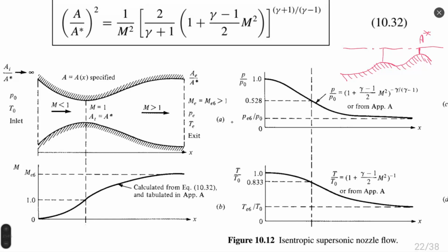And in the previous extreme minimal, this part where we had the minimal area of flow is not a throat anymore. Here, the Mach number will be different from Mach 1. It can be supersonic or subsonic, depending on many conditions.